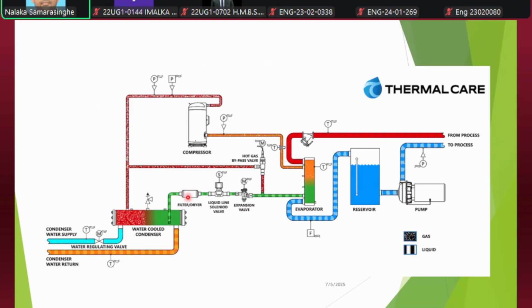Here you can see the condenser coil and evaporator coil, they are inside these 2 heat exchangers. Here we have the evaporator heat exchanger, and here we have the condenser heat exchanger. In this heat exchanger, inside you have a large evaporator coil. Now you can see, after the expansion valve, you have the refrigerant at a lower temperature. It will be going into the evaporator.